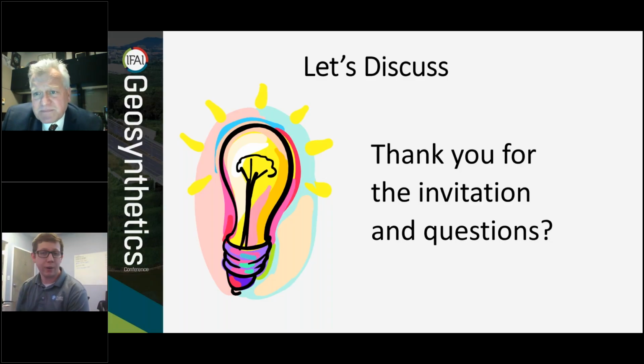Thank you. Yeah, I would also add, I completely agree that it's regional. Every area is a little bit different. Every project's a little bit different. Just to reiterate what George is saying, your preparation is critical. We deal with lots of projects in different areas, and anytime that we have an issue with vegetation establishment, I can almost guarantee you that if you start going and asking through the questions, there's something that's missed. Whether it's did you prepare your subgrade and make sure that it's not void of any organic content or has the wrong pH. You have to have good organics. You have to have the right pH for vegetation to germinate and establish.